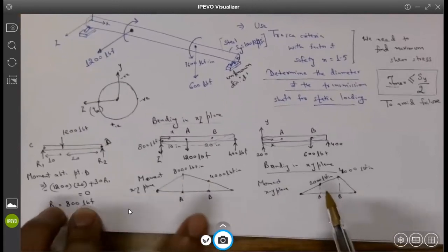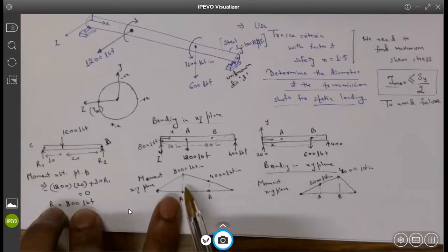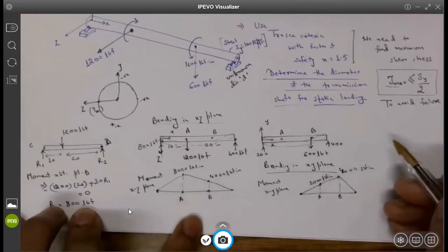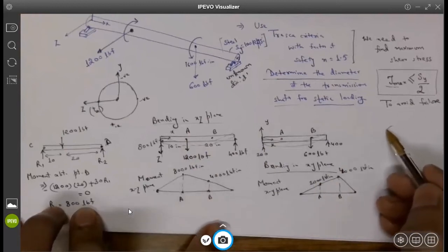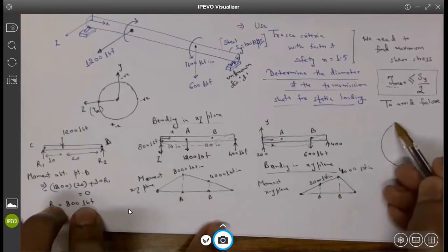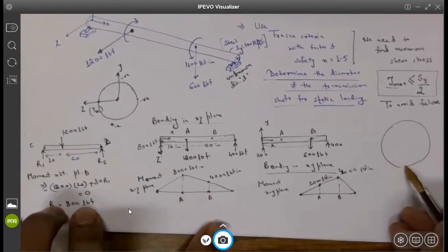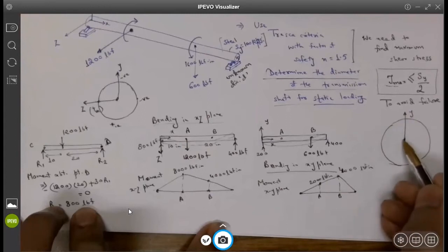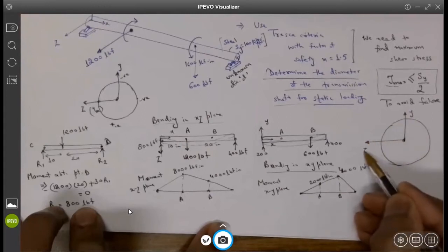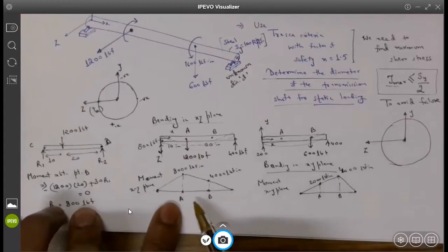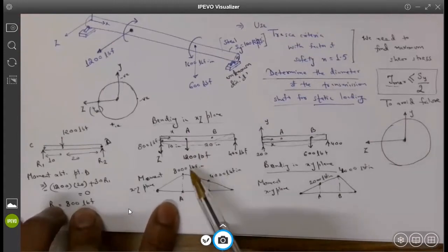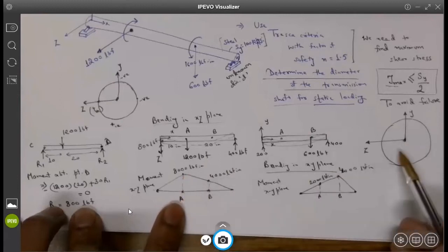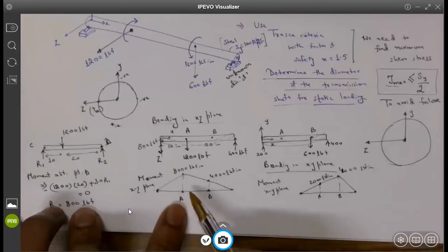So let me help you see how we combine bending moments appearing in 2 different planes. For doing that, we have to look at the specific cross section. We have our y-axis here and our z-axis here. First we focus on the XZ plane. In the XZ plane, you are applying 8,000 pound force inch at location A. So we are drawing this cross section at location A.